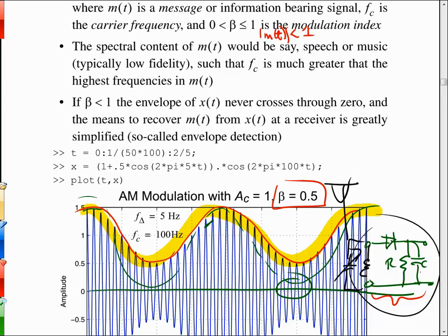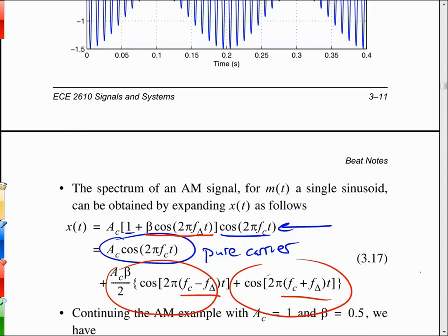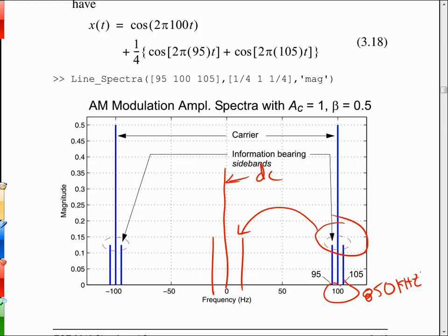Right? I mean, you can say that's true as well. For the military, AM radios would be utilized for certain things, but they don't have certain amounts of robustness for jamming and so on. But guess what? AM modulation is used in a very important application still to this day, and that's the aircraft bands that are around 110, 115 megahertz, where AM signals are located. Just above the FM broadcast band is where planes communicate with the tower through an analog voice means.